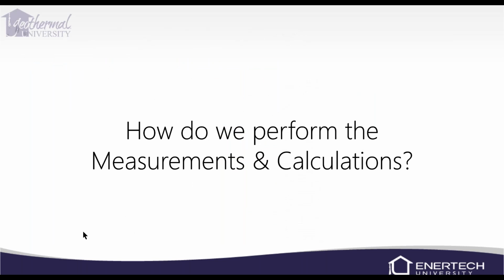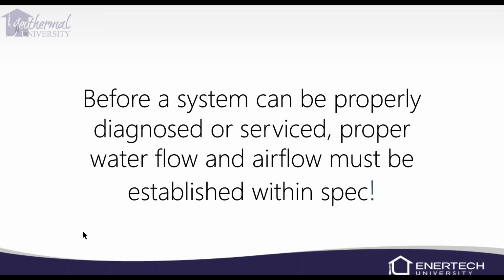So how do we perform the calculations and the measurements? Before a system can be properly diagnosed or serviced, we must establish that we have airflow and we have water flow. Now, when we do pressure drop, that's going to tell us water flow. Got to have pressure drop. You don't have pressure drop, you don't have water flow.